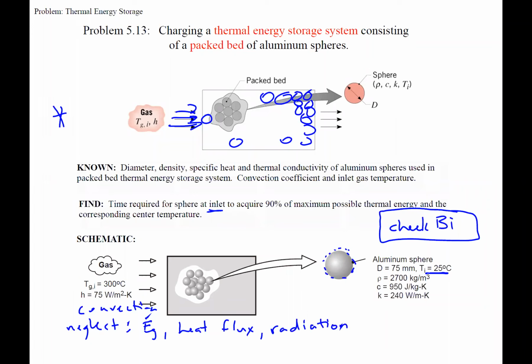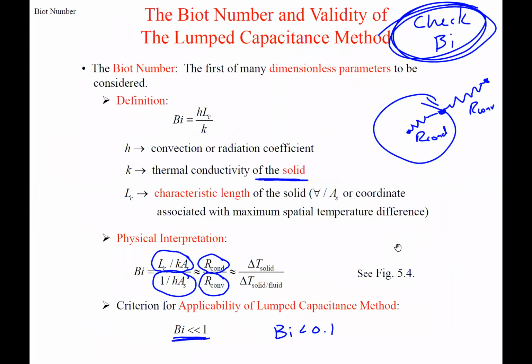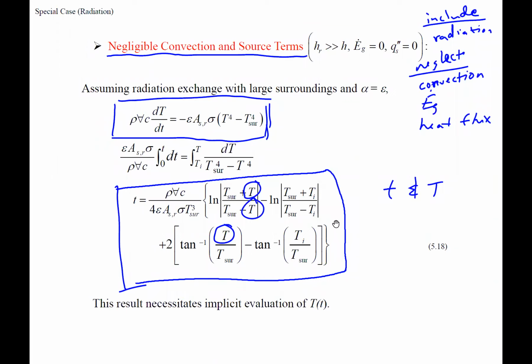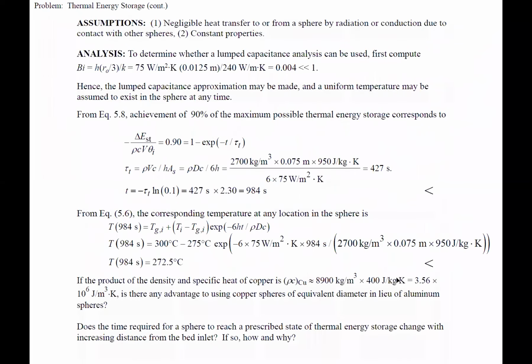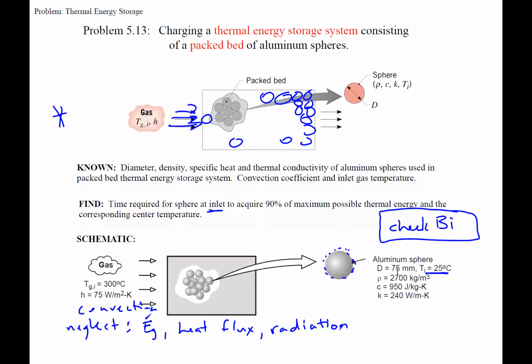All right, so they didn't give us any parameters for radiation, so that's a big hint in book problems. In practicality, what you want to do is check convection versus radiation, where h is much greater than h_r. Okay, h_r, you can find the equation for that in chapter 1. It changes the radiation equation that has temperature to the fourth into a linear equation where we can utilize it for h_r. So that would tell us to neglect radiation if convection is dominating versus radiation.